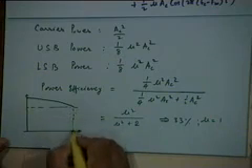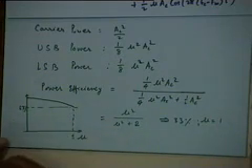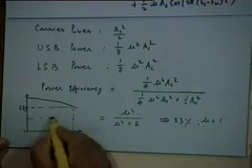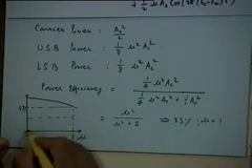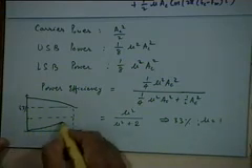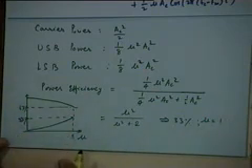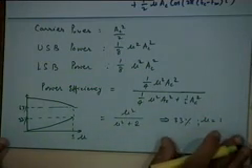When you take mu equal to 1, 67% of the power is in the carrier, right. As far as the sidebands go, at mu equal to 0, there is no power in the sidebands, and at mu equal to 1, 33% power is in the sidebands, right. So, that is the profile that you have.